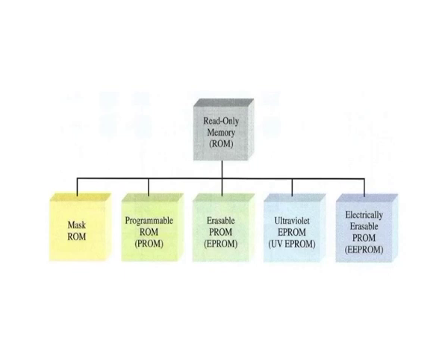The EPROM or erasable PROM is strictly a MOS device. The UV EPROM is electrically programmable by the user, but the stored data must be erased by exposure to ultraviolet light over a period of several minutes. The electrically erasable PROM can be erased in a few milliseconds.